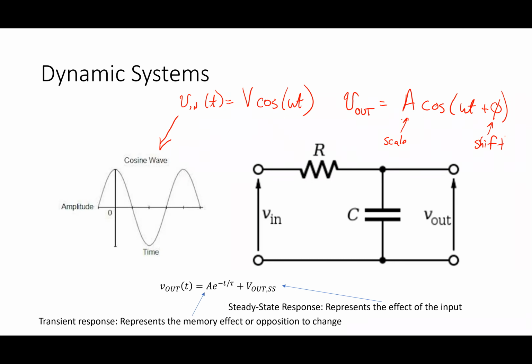One option is differential equations, right? So I can use differential equations to solve this. If I wanted to do it, it would be RC dVout/dt plus Vout equals Vin, right? It would be this thing, and you could get that from KVL, right? No one likes that, right? I've got to guess stuff. It's ugly. What's the other way that you've learned in 2112 and that we used in the project too?